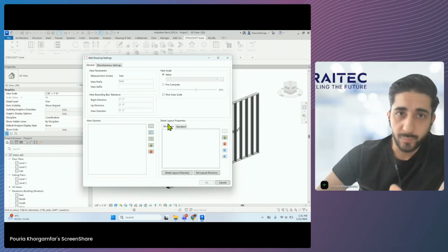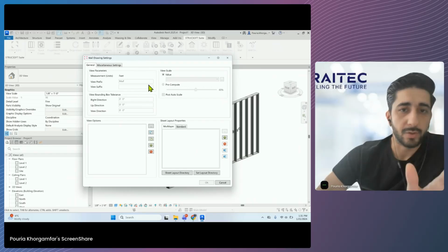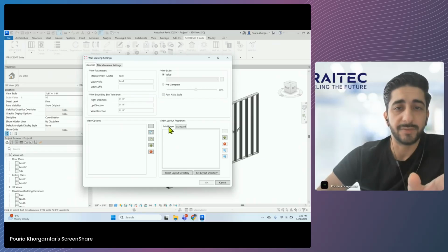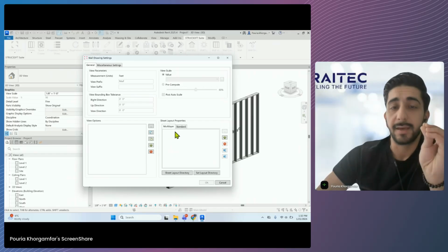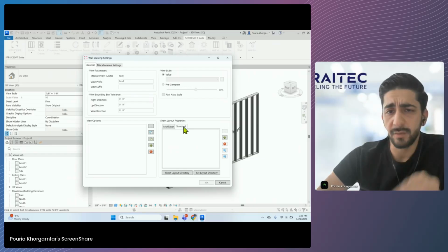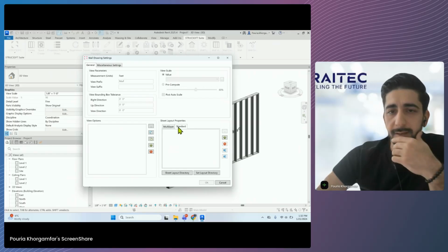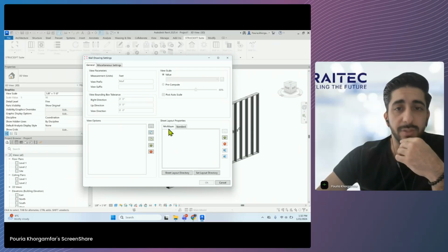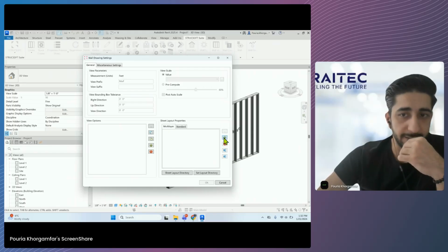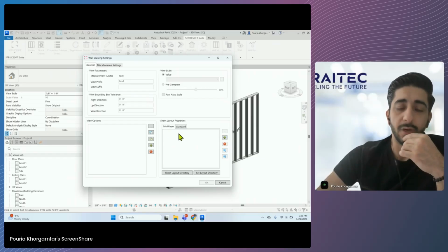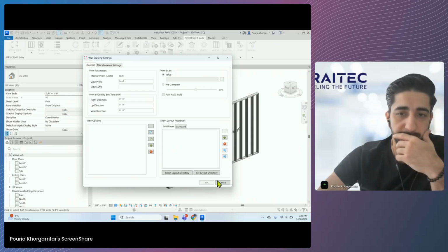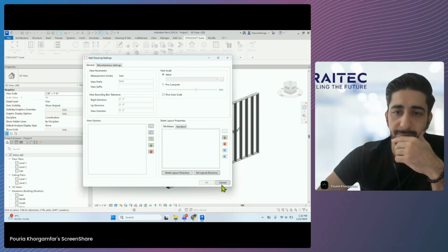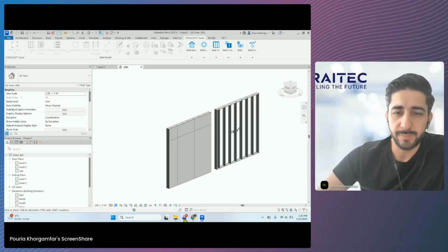Through this method, you are going to need to have the shop drawing for the sheathing, and also for the structural layer, created under multi-layer. We are eventually going to eliminate the standard one, so it's highly recommended to use multi-layer for creating your shop drawings for your structural layer and also the sheathing layer. So multi-layer it is.